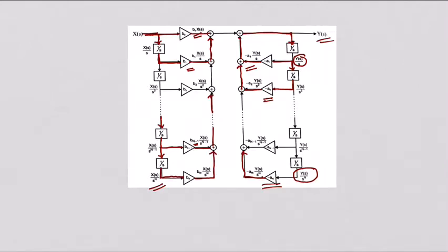So this is how the Laplacian domain representation of a continuous time differential equation is built in terms of the s variable: 1 by s, 1 by s, 1 by s. So 1 by s is the important module. Multiplier is another important module. Also adders are present in this chain, to produce an output from x of s. So this is called direct form 1.